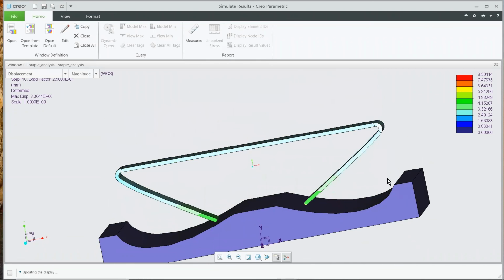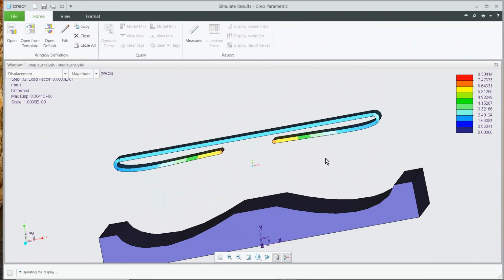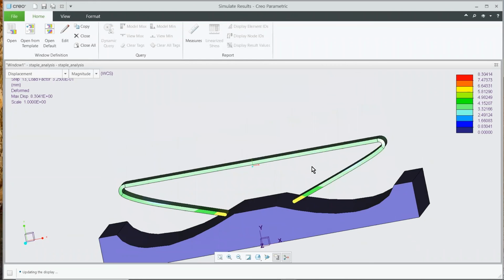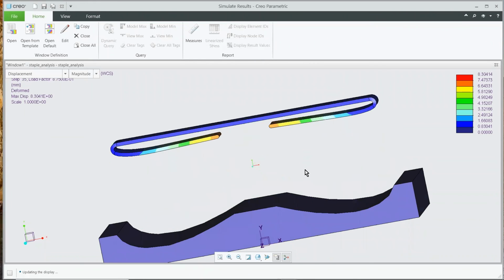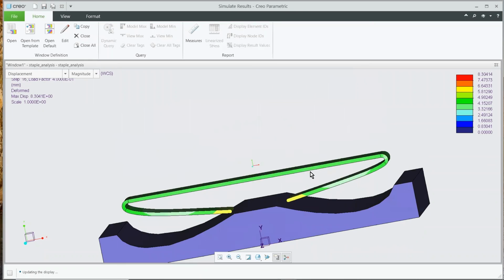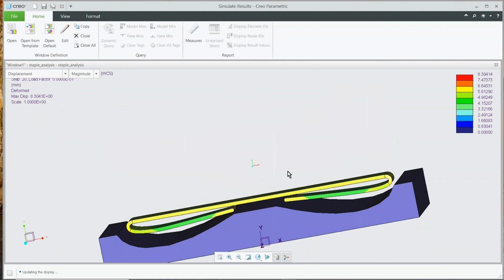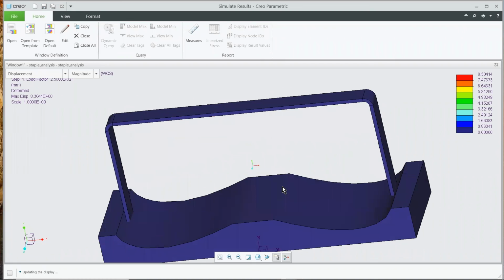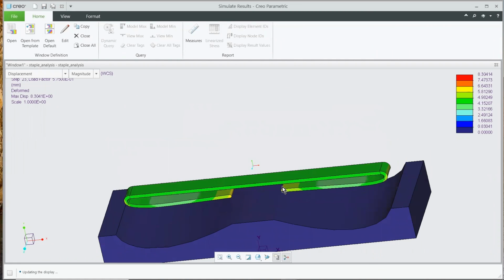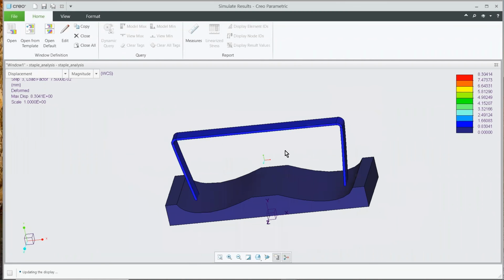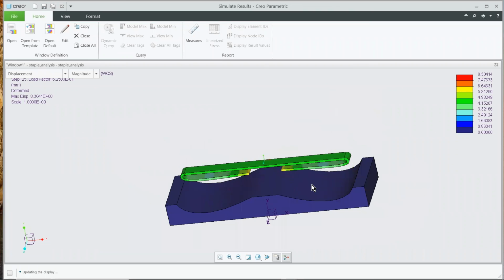So I never really needed to put that extra contact in, but that's fine, right? It's only when they come in contact, I should say, that it really comes into being used in the calculations. But here we can see the deformation. We can see how this is behaving, and we got an accurate representation. And again, because it stays bent, it's a plastic analysis.